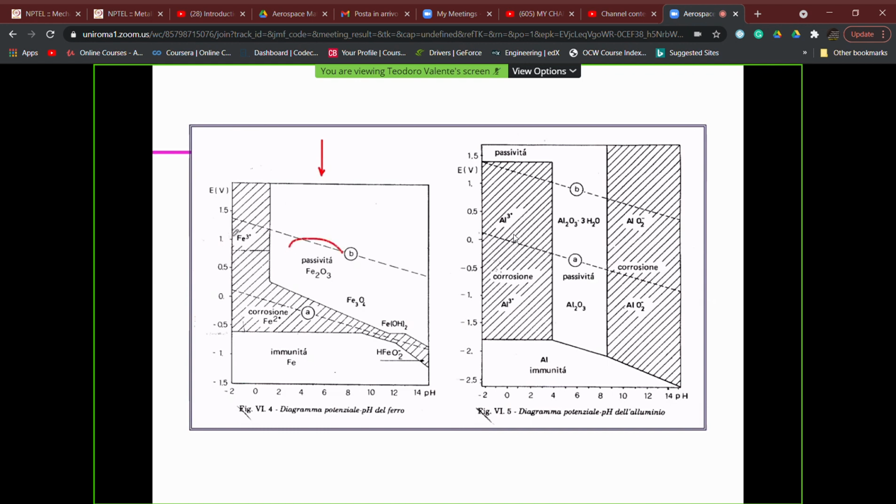You see the areas in which the ion is stable are areas which are somehow underlined. And if you see here, if we move all over the range of the pH value, we do have the possibility to match the stability of the ions. And this means that iron in this condition can corrode. And this matches our experience. Then another thing is to understand how fast the corrosion is, that is the value of the corrosion rate.